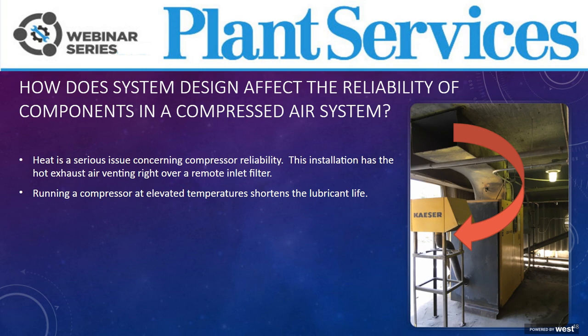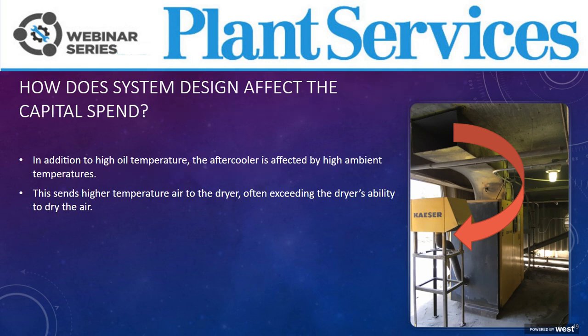In this case, the customer was losing his lubricant in a matter of months, and eventually was losing air ends, simply because he didn't put the intake filter far enough away from the exhaust duct.